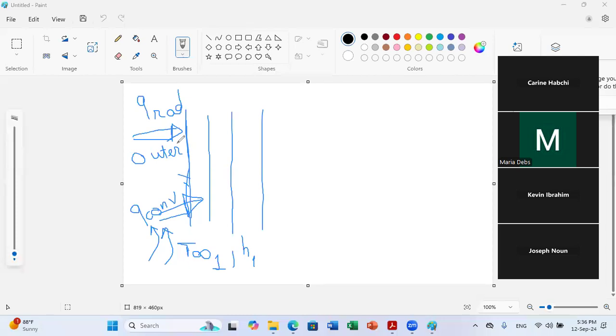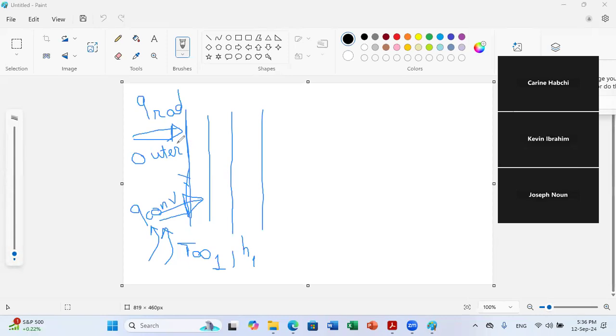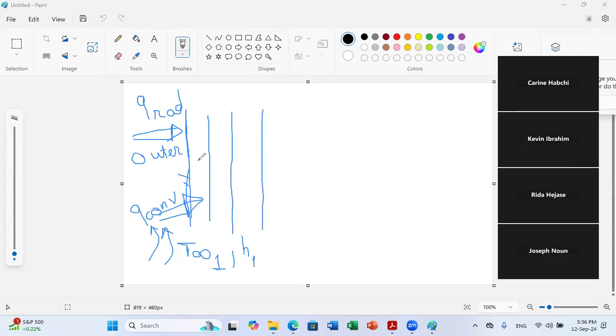Now, if we consider a steady state case, so whenever I say steady state, this means that there is no variation with time. We can consider that this heat will be transferred through the envelope by conduction, because our envelope, let's say, is made of several solids, and we can divide it into several layers, A, B, and C. So if you just look at buildings in construction, you can realize that they can put several layers.